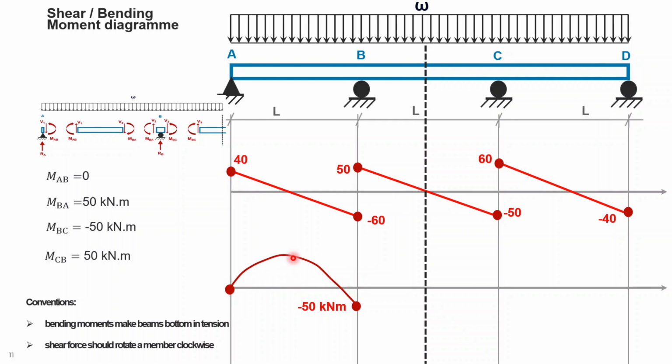And we choose this one because we know that when we come from the shear force to the moment diagram, it's like integration. And vice versa, when we go from the moment diagram to the shear force diagram, it's like taking a derivative. And here you can see the derivative of this diagram should be positive, and here the derivative of this diagram in this region should be negative. So based on the derivative of this diagram, which is the shear force value,